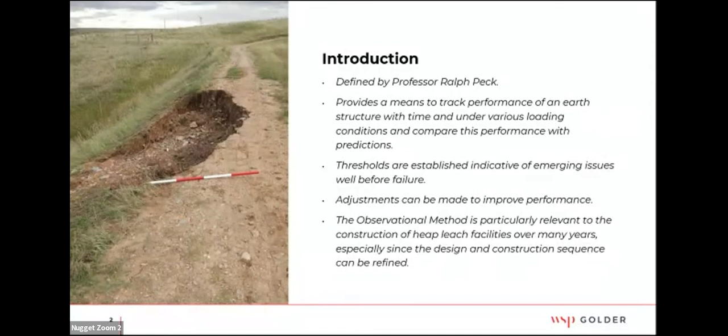Using this method gives us an opportunity to evaluate geotechnical conditions. You could also use it for metallurgical, which is a different set of tests. But during the operations of the facility, it lets us confirm that what the design engineer assumed or estimated at the design phase is actually happening in the heap as you're operating, right?